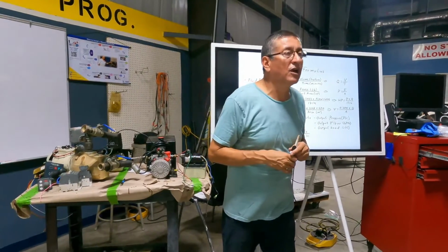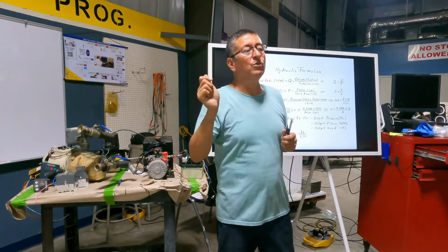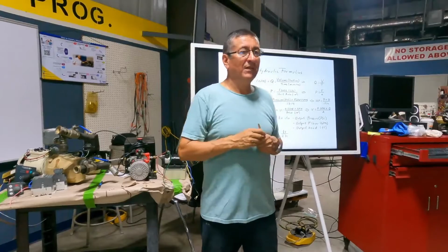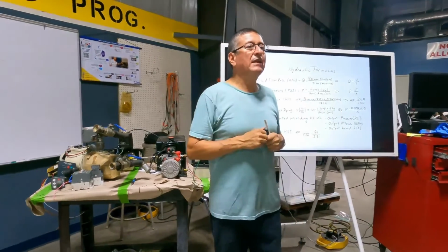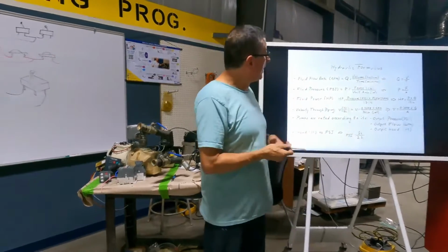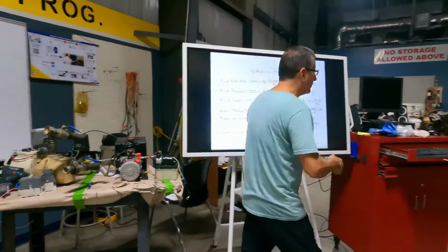What is the formula for torque? Torque is equal to horsepower times 5252 divided by engine RPMs. Those formulas should be impregnated here for the rest of your life. Okay, with that information, we are ready to calculate. I have a good example here.